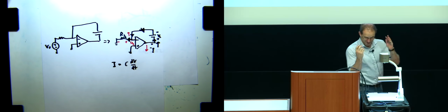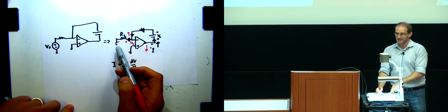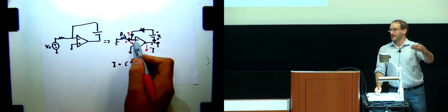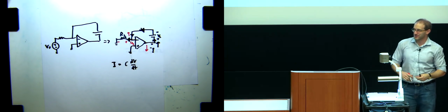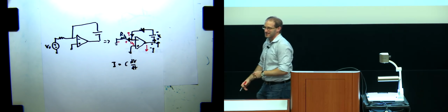So here what you're doing is a quote-unquote incremental analysis of, all right, if I don't know whether or not there's negative feedback, I need to check what is the influence of a change at the output, going back through the op amp and coming back to the output. So that's why I'm allowed to say that U2 here is not necessarily strictly 0 volts, because golden rule number 2, I've not actually verified that I'm in the conditions that would make that make sense yet. Does that make sense? This is a good general question, because when you are checking for feedback, both the sign of it and whether or not it exists, you can't invoke golden rule number 2. Golden rule number 1 still holds. Number 2, you don't actually know yet.